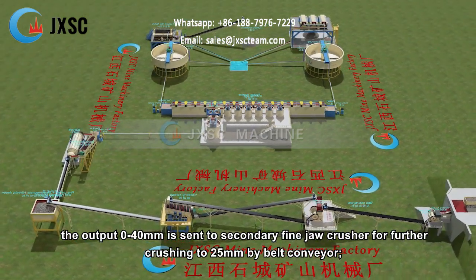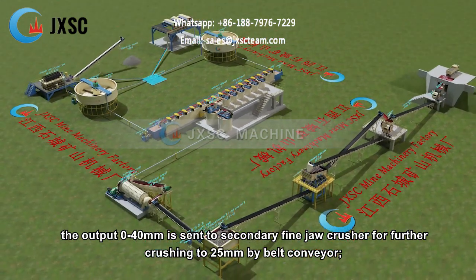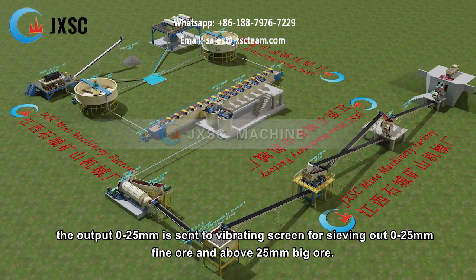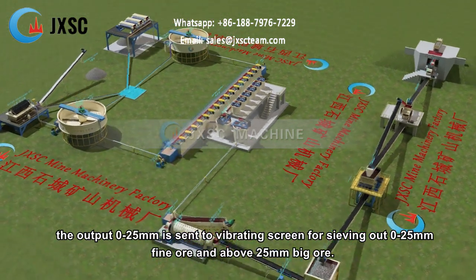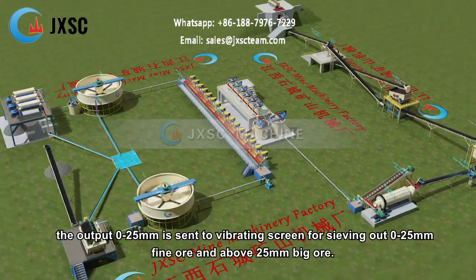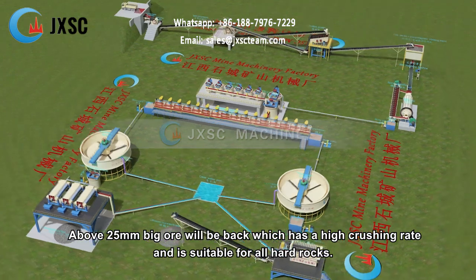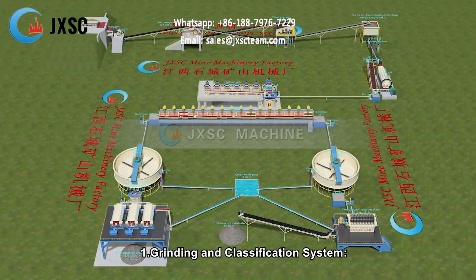The output 0 to 40 mm is sent to the secondary fine jaw crusher for further crushing to 25 mm by belt conveyor. The output 0 to 25 mm is sent to the vibrating screen for sieving out 0 to 25 mm fine ore and above 25 mm big ore. Above 25 mm big ore will be sent back, which has a high crushing rate and is suitable for all hard rocks.